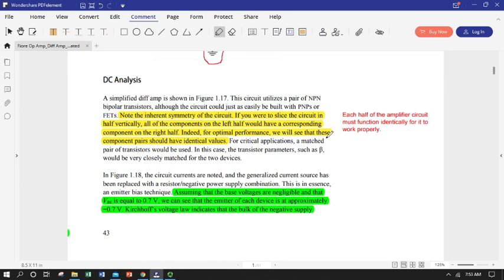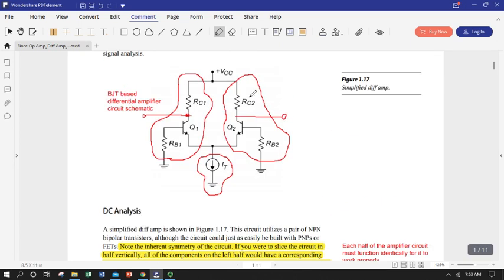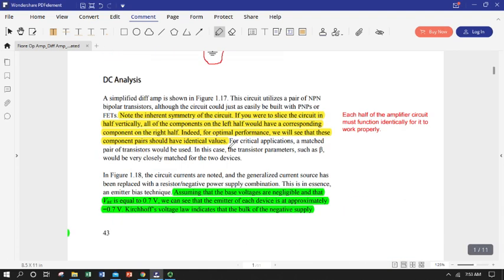And to get that, we have to make sure all of those components in the circuit are the same. So resistor tolerances get very important here. Resistor response to temperature, most importantly beta response to temperature, is very important. So circuit design to make the amplifier beta non-sensitive gets very important here.